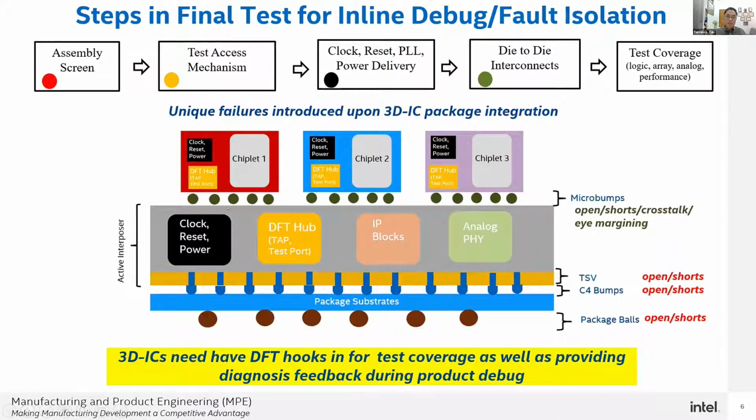So the standards need to specify how the interoperations need to be handled. For example, I mentioned, how do I want to achieve isolation? What is a mechanism to achieve isolation? What kind of gating? Is it through certain gating, through certain active cells? Maybe all your boundary signals need to have some kind of overrides. So there are many ways of achieving some kind of isolation schemes. That's what I mean by standards.